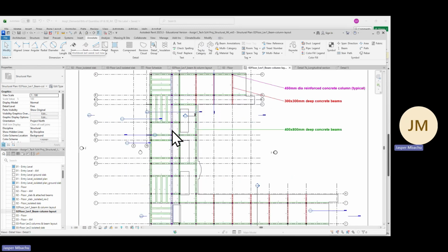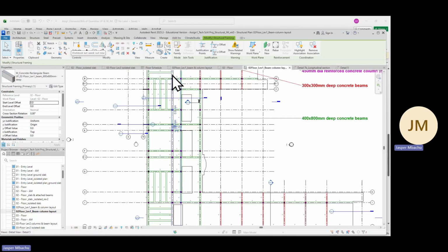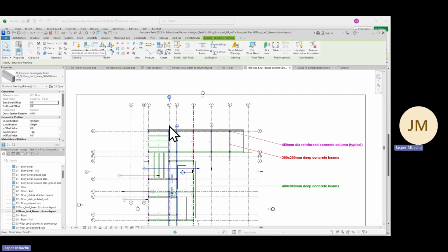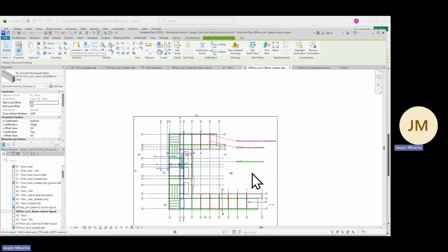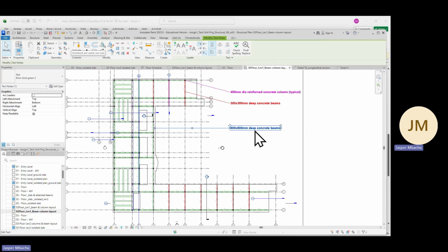The blue ones are this one, and they only occur on grid line 1.1. So we also annotated that it occurs only on that. So select one instance of this, hold down on control and drag.